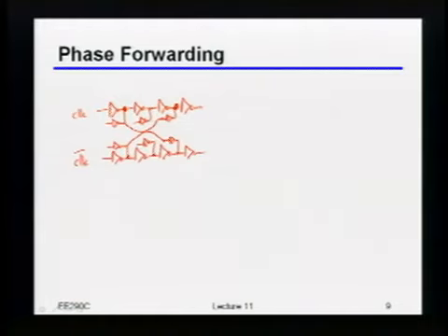Well, the idea here now is that I'm still going to guarantee that things are inverted from each other, because by adding those extra little inverters, I've made it really hard for you to start up in a bad position. But now notice, this thing starts transitioning before this one even does. Or, to be more precise, this starts transitioning before this inverter actually gets its input signal. But it is moving in the right direction, because you know that, for example, if this starts going high, this is at some point going to have to go low.